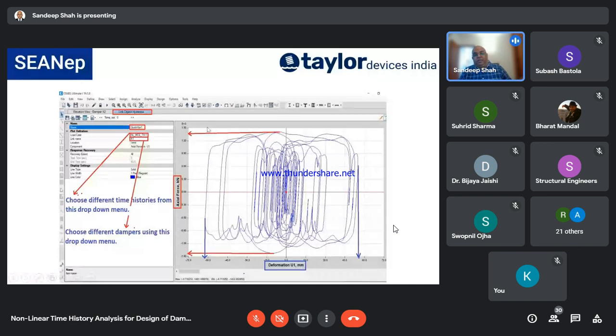After I incorporate the safety provisions of the lambda minimum, the lambda maximum, and also the redundancy factor, which increases my force capacity by 30%, it will give me a higher result. So ultimately, when I go and order the damper, it will give a higher result than what is being shown by these graphs, because these, you must remember, are the nominal structural properties, and those properties are giving you these values.